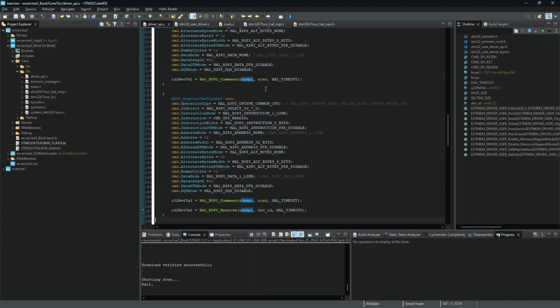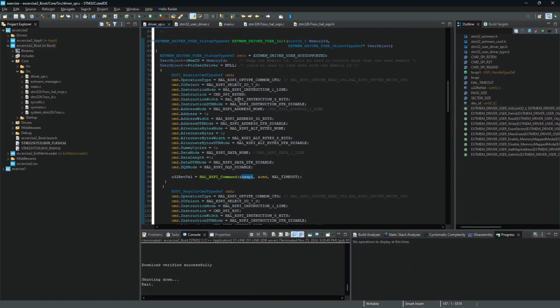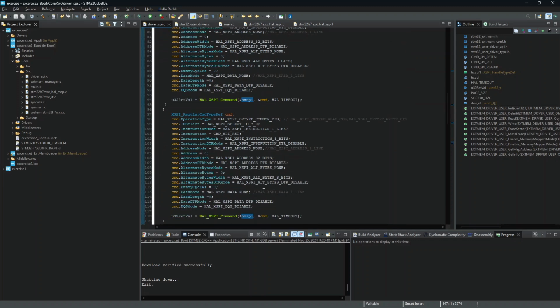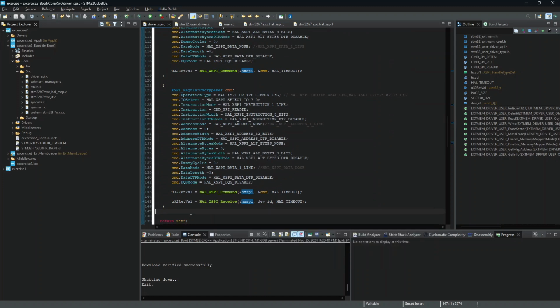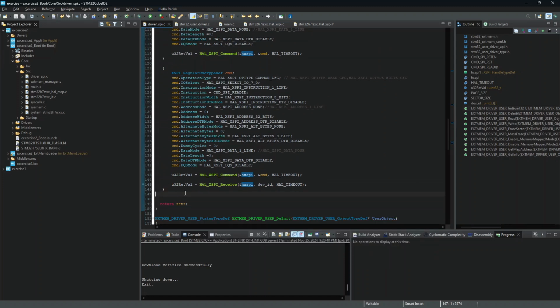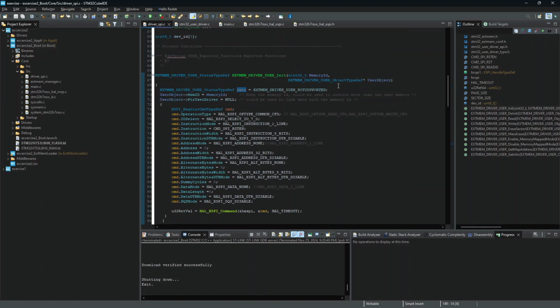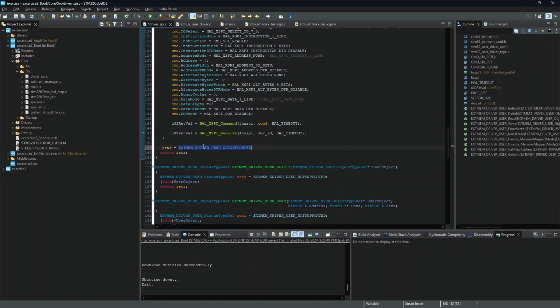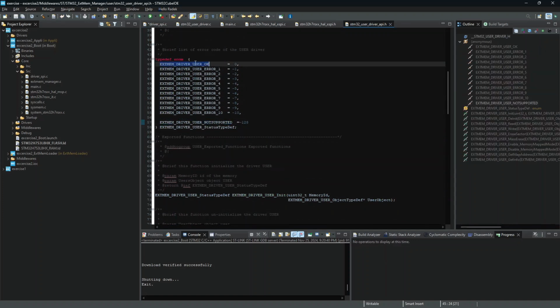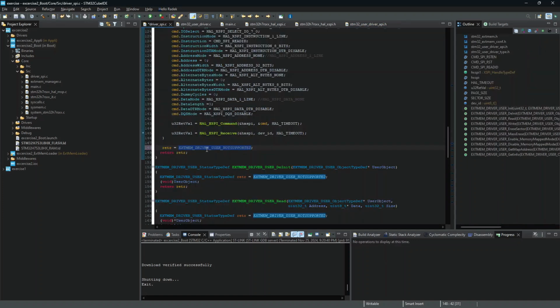We have now a correct initialization sequence. So we enable the reset, we reset the memory, and then we do reading the ID, which is optional. Sometimes it's good to check that the read is working correctly. And in the rest of this function, we need to return the return parameter, and by default, the return is marked as an error. So I will change it here into something meaningful that we are okay.